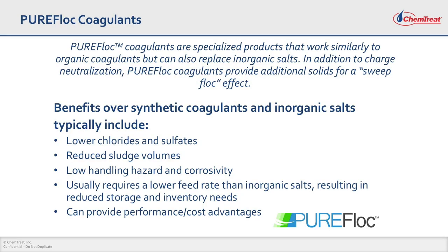PureFlock coagulants are specialized products that work similarly to the organic coagulants, but can also replace inorganic salts. And in addition to the charge neutralization, they also provide this sweeping effect on residual pin flock that may remain in your water. So what are the advantages? The advantages are that you provide less chloride and sulfate into your makeup stream.